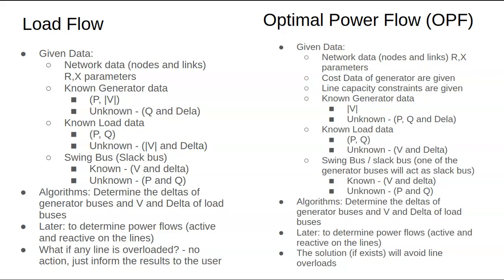Optimal power according to optimal power flow, like that. Capacity is how much? It's 400, but the output of OPF is saying you generate only 250. Now you can ask a question: no, I want to generate 400 from there, but the optimal power flow may not be able to solve.